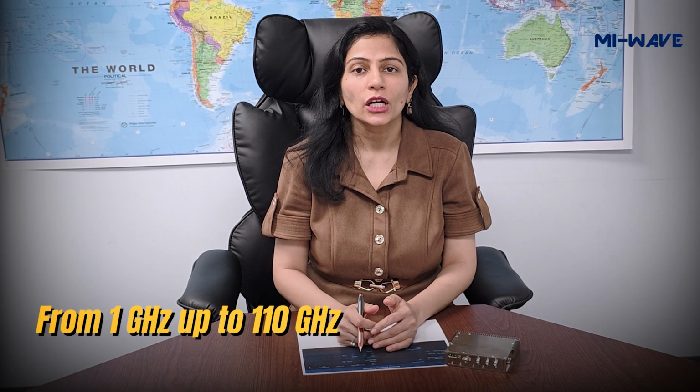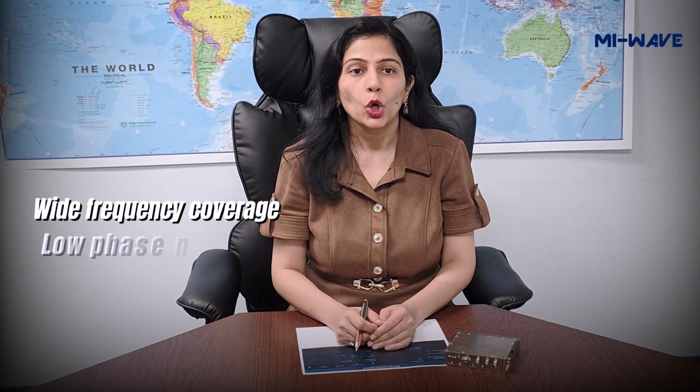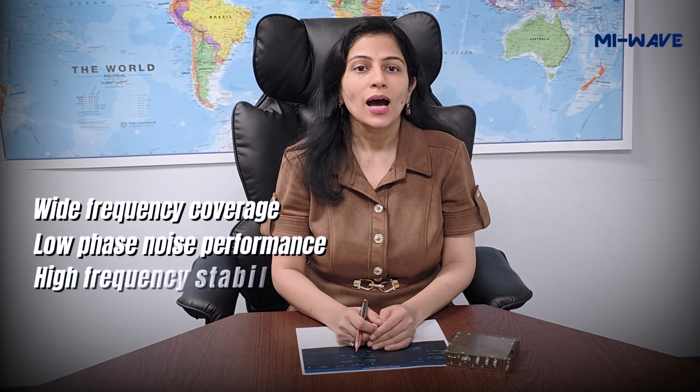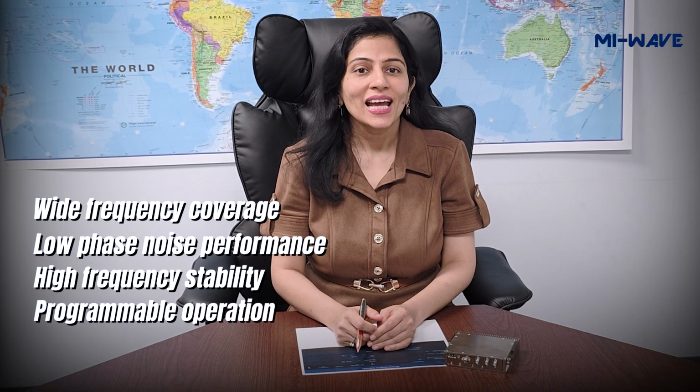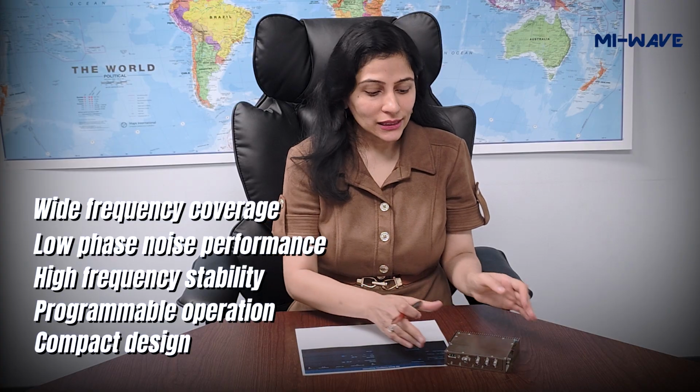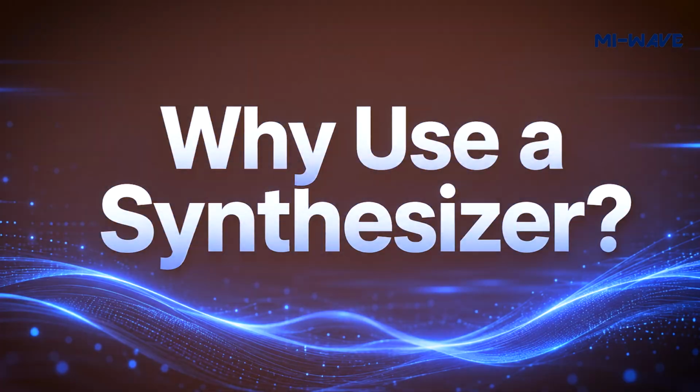Depending on configuration, the 958 series provides ultra-wideband frequency coverage from 1 GHz to 110 GHz. The synthesizer combines wide frequency coverage, low phase noise performance, high frequency stability, programmable operation, and compact design in a single RF source.